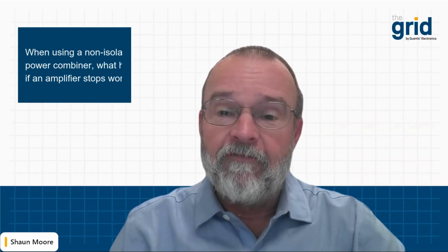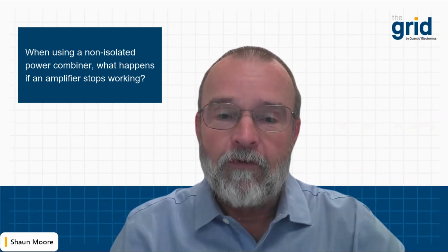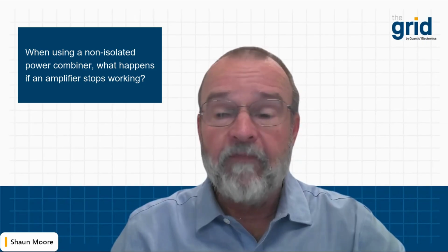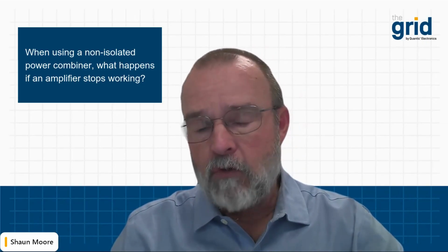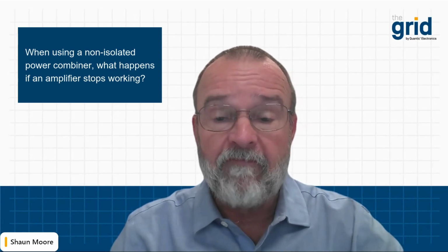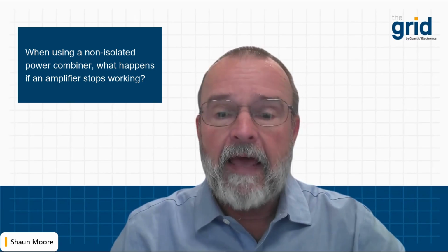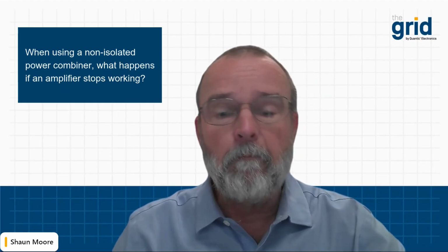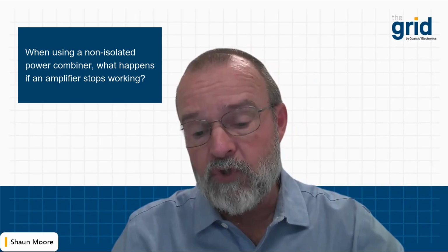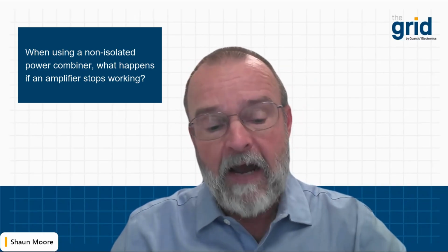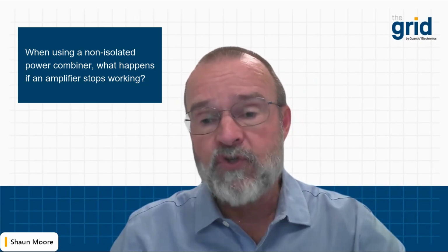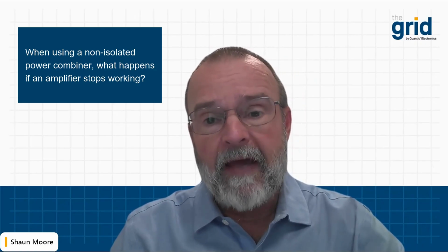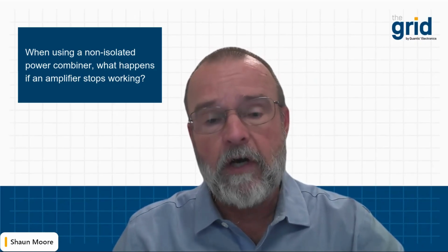Okay, this is the fear of every engineer using this sort of device, because once that amplifier goes offline, its match goes completely out the window, and you end up with a very high VSWR, and half of that energy that's still left in a two-way combiner example gets reflected back to its source. With half power, the VSWR of that other source goes to something like 5.8 to 1, I think, which is really quite bad. So if you lose one amplifier, essentially you lose the entire rack.